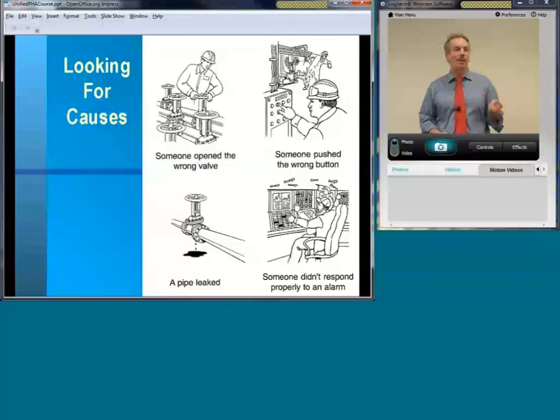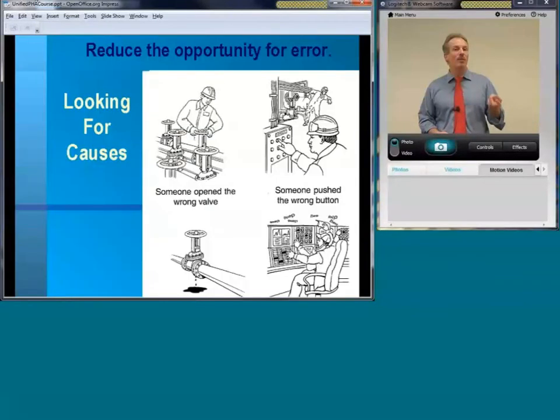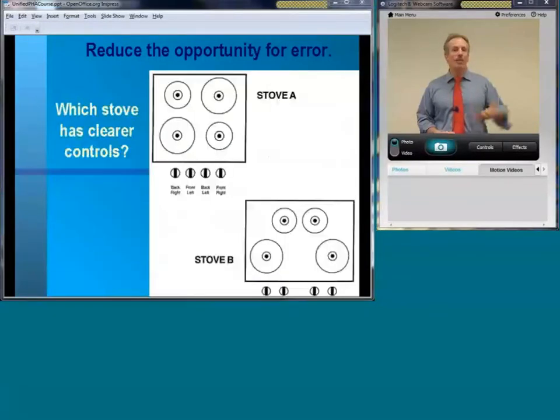And while we're talking about safeguards, if you've got multiple alarms, you've got to be careful not to give multiple credit for multiple alarms that just tell the operator to do the same thing. Even if one alarm goes off, it's a clear cause, and it leads to the operator taking the correct corrective action, that's fine. There's a certain human error probability associated with that. Two alarms, if it's clear and directly associated with the causal event, can also help the operator rapidly diagnose the problem and take corrective action.